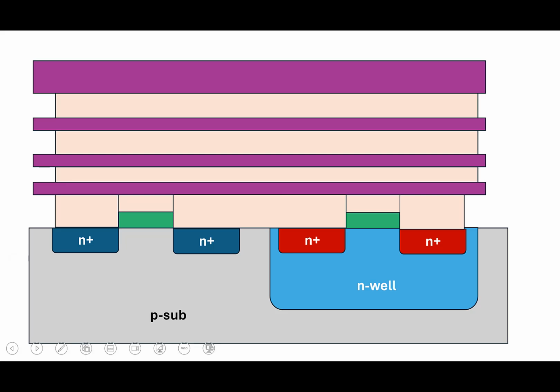Okay. And let us say now you want to connect this. Let's say I call this the drain of the NMOS transistor, and the drain of this PMOS transistor. I want to connect these two. But remember that this is a semiconductor. For connecting it, I have to connect using a metal. So we usually have what is called a contact. Right? And from this contact, you have to connect to this metal and then make this connection.